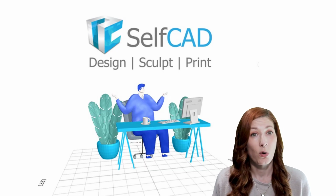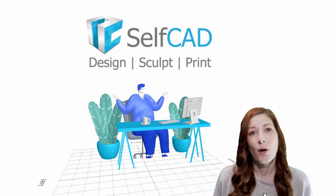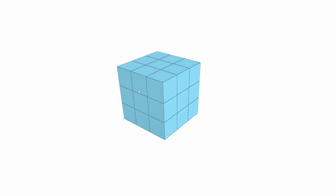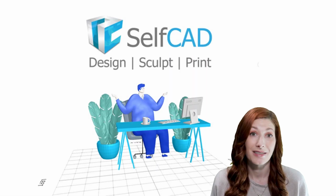Holes in the topology. Before we check for any holes in the topology, let me explain the issue first. Holes are a problem because 3D objects need to have a closed volume, also known as manifold or watertight. Any hole in the topology will make it lose its volume, making it impossible to use some editing tools. In a simple 3D object, holes are obvious, and you can spot them just by zooming in and looking at the object from all angles. However, the more complex the object is, the harder it will be to see if anything is missing.